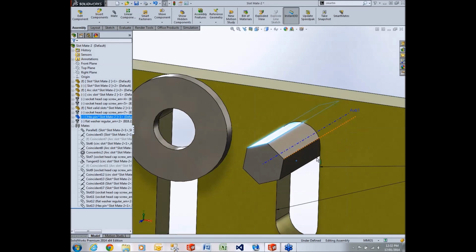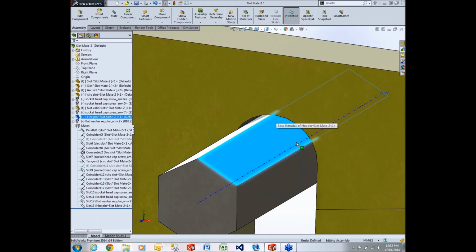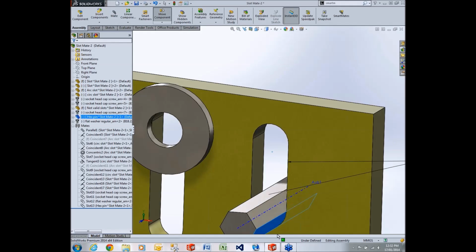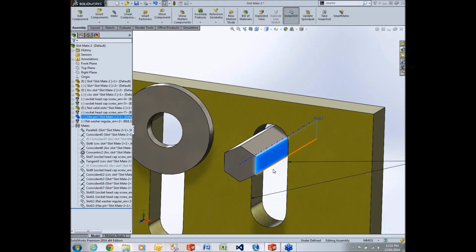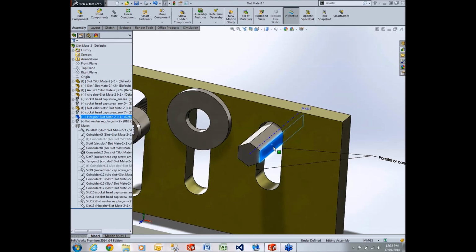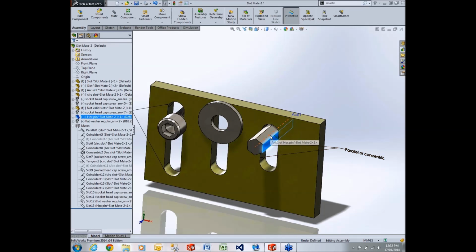What you will notice is that it is allowing some interference at the points here. What it's essentially doing here is allowing the axis to move along the sort of axis plane, I guess you could say, of the slot itself. So in terms of sizing, it's not performing any interference detection or anything like that. It's allowing the axis of the hole or cylinder or the axis itself that you select to move along the center, the distance, I guess, between the two center lines of the slot.